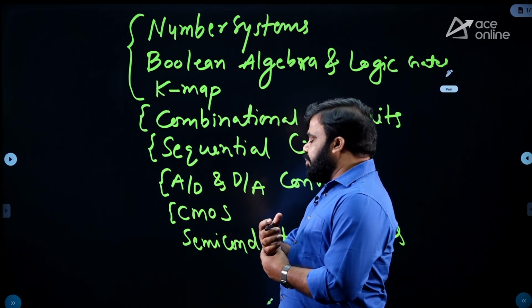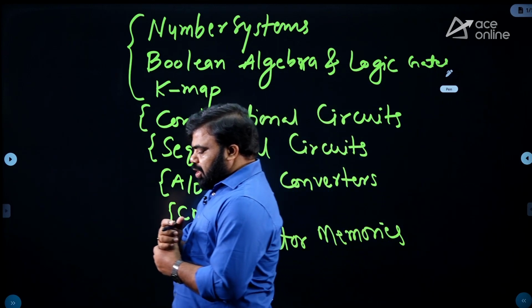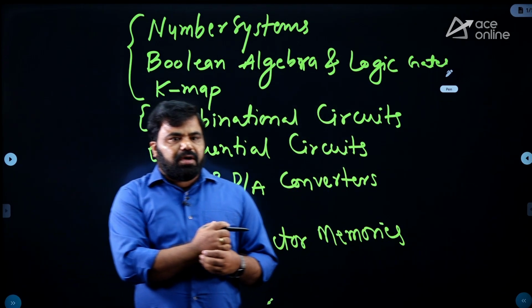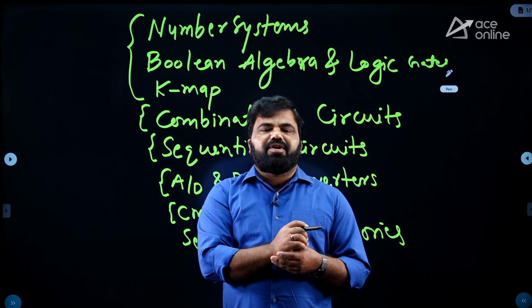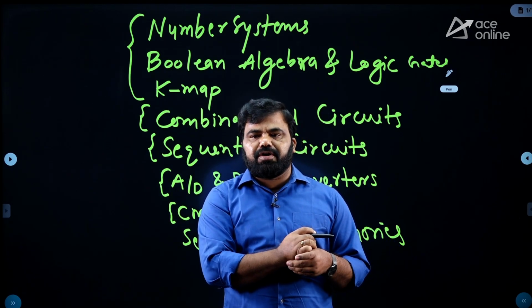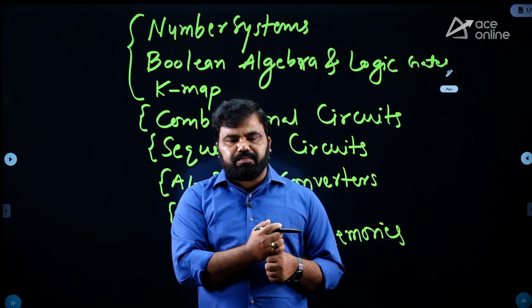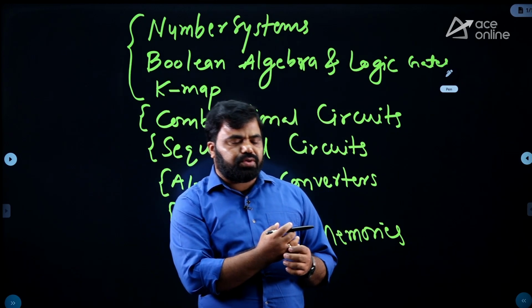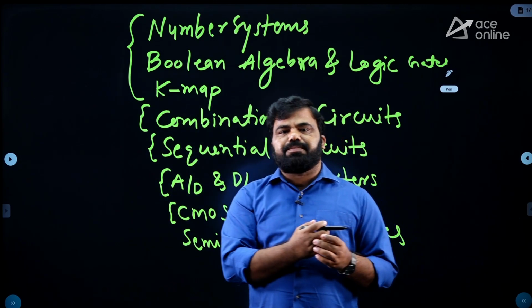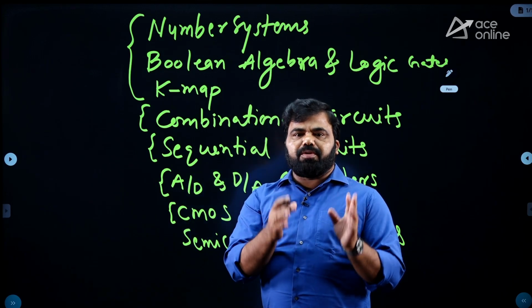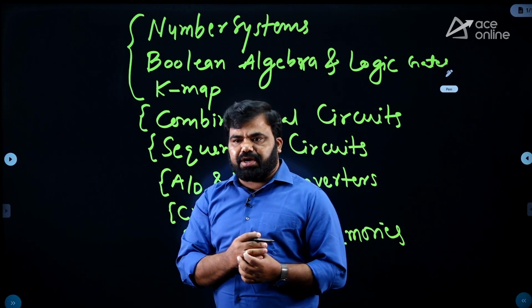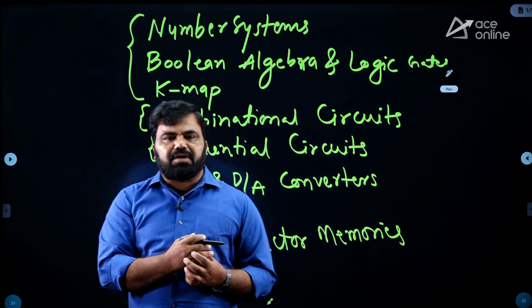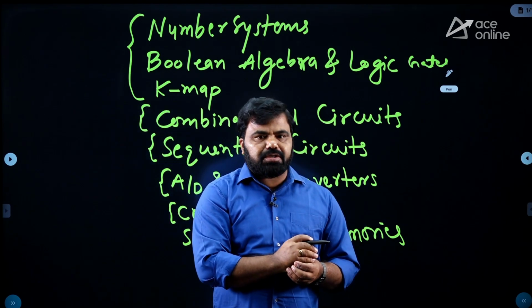And coming to memories, when specifying a logic function, they may ask what memory size is required to store these logic functions, like ROM. What is the ROM size required to store these logic functions? Or by giving a ROM implementation, they ask for so and so address, what is the data we are getting? We can analyze that from the discussions we had.